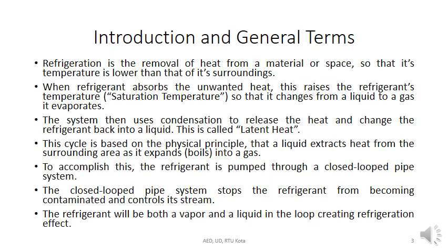So refrigeration is the process of removal of heat from a material, and generally it is from a space, to control the temperature, and it shall be lower than the surrounding temperature. So when a refrigerant absorbs unwanted heat or additional heat, it raises the refrigerant temperature, which is known as saturation temperature. When saturation temperature occurs, the change from liquid to gas, means from one phase to another phase, occurs.